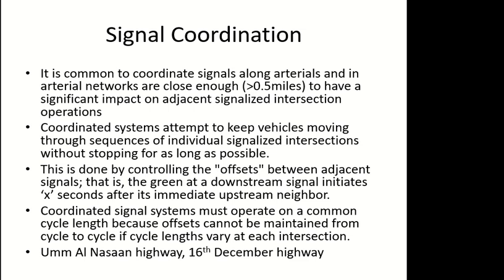Coordination means what? When we are designing them, when they are planned for timing, when the timings are being fixed, we fix the order as well. So after the first signal, the second will become green, then the third will become green. So they will become green in order. Okay, and you should understand the logic behind it. When the car passes the first signal, it will go to the next one, so the next one should become green. Then it will go to the next one, then the next one should become green. So they will keep on becoming green in sequence.